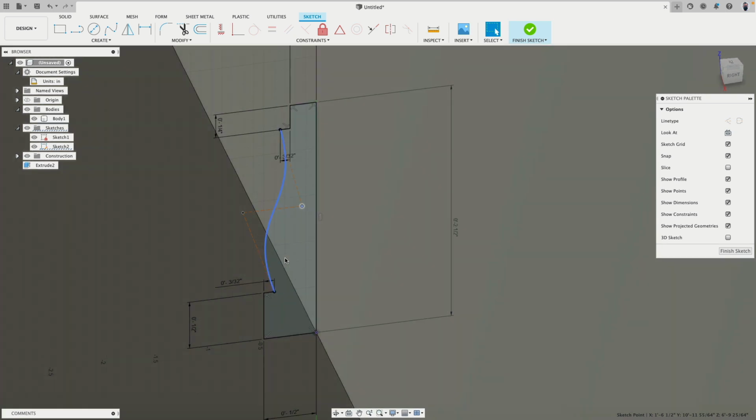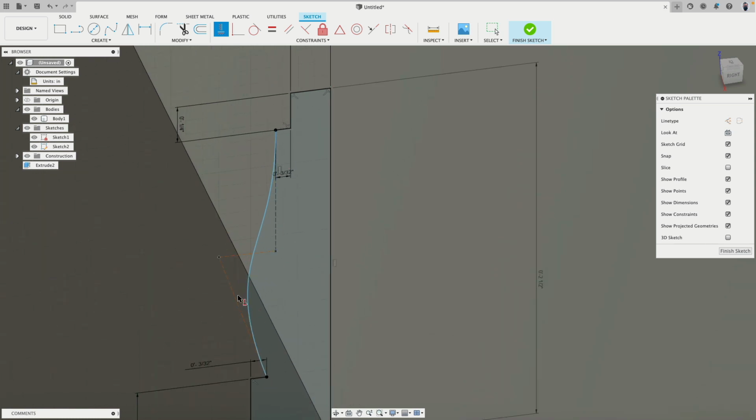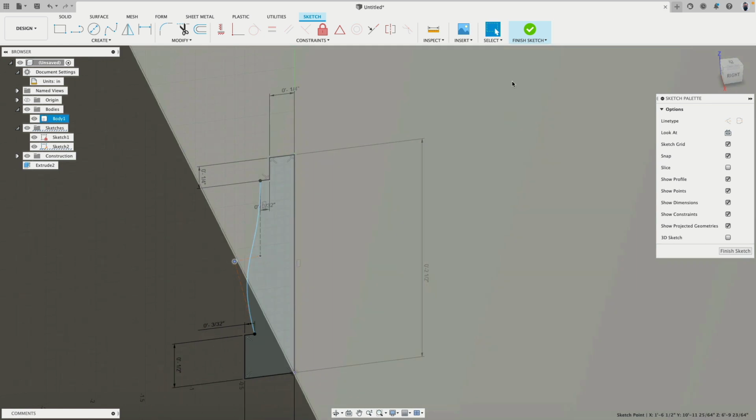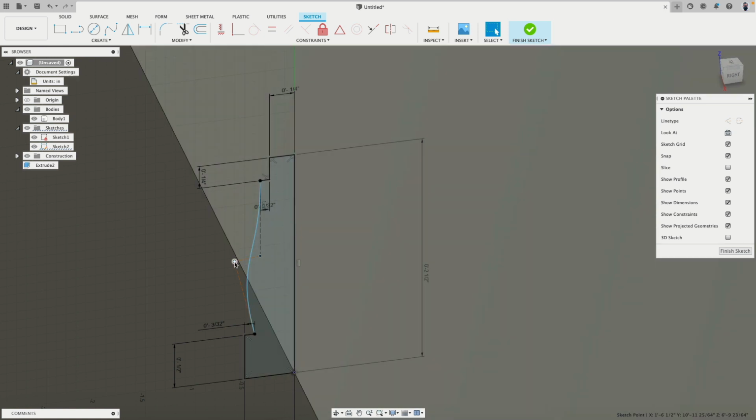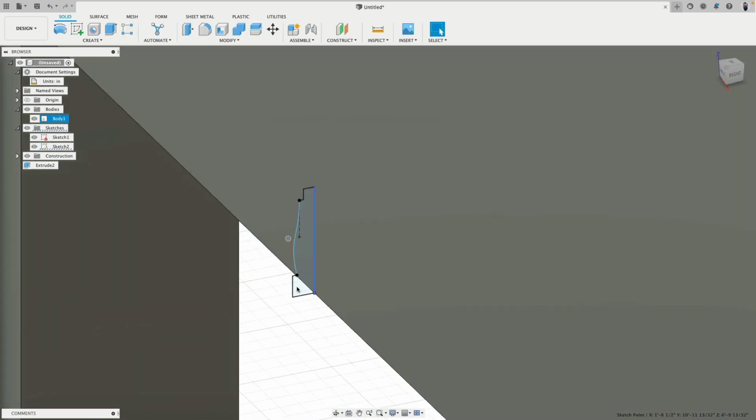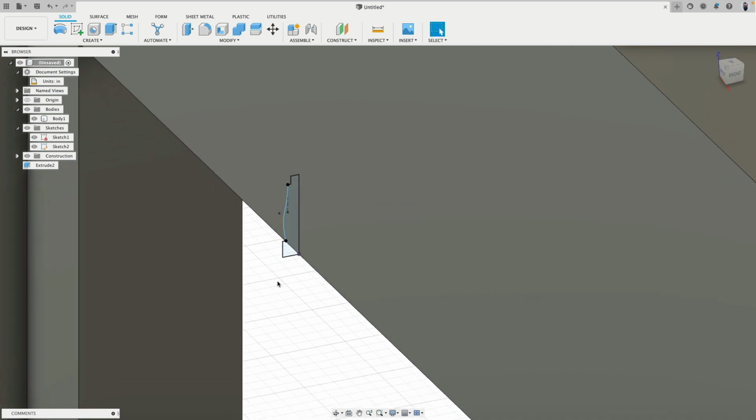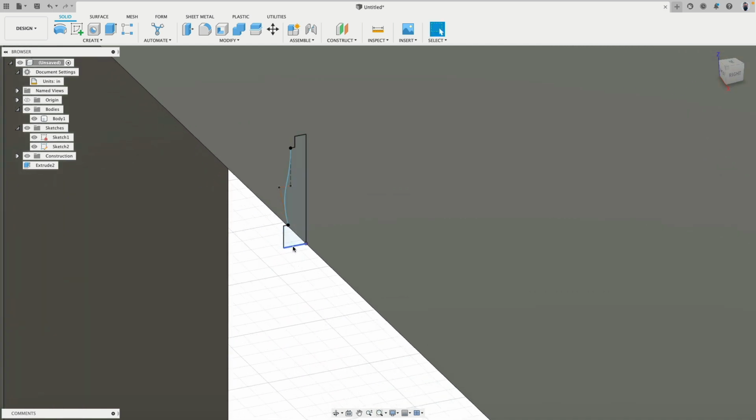This goes in, this goes up. Maybe this I want to be vertically aligned. This vertically aligned, but then this is too tight, too narrow, undo. So maybe this I push out a little bit. Very good. We don't want to spend too much time on it, but you can see the position of this point really sculpts that curve. Cool. Okay. That's it. For those who are new, and I'm curious, why is this black? Why is this blue? All these lines have dimensional constraints. When this blue doesn't, that's the reason why it's blue.